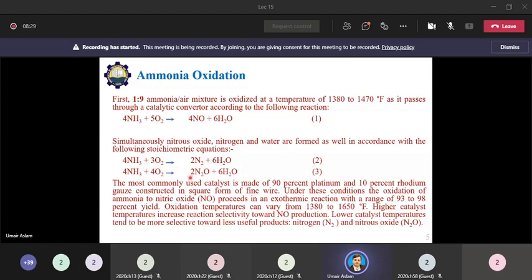Usually, in the presence of the catalyst, if we do not get the required temperature range in the reactor, rather we have lower temperature than the required reaction temperature, then reaction number 2 and 3 are favored. And if the temperature of the reactor is in the desired range, then reaction number 1 is favored. If we have good control, the yield in this converter is 93 to 98%.